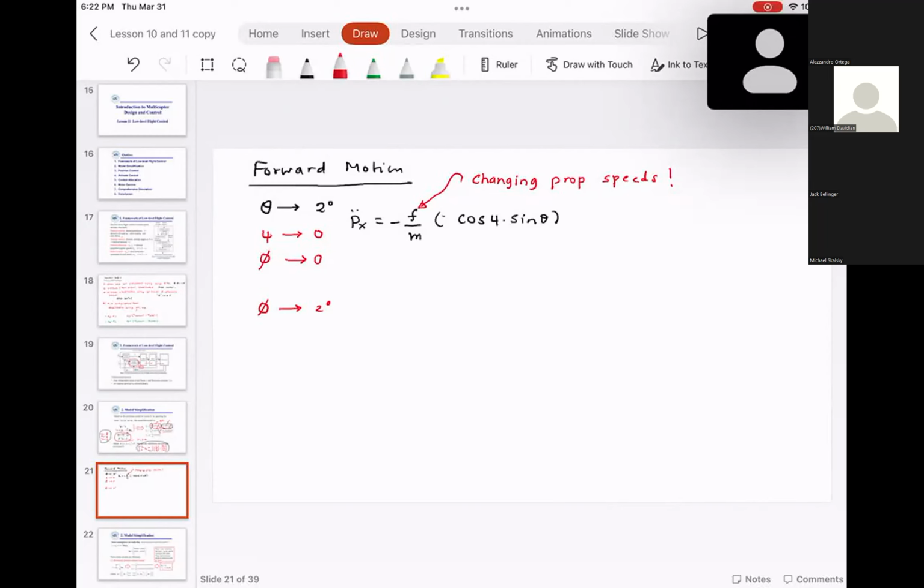So I hope that you will build that Mambo pendulum, and then I want you to observe that, assuming you are able to get those coefficients correctly, your Mambo would be stabilized for maybe 10 to 15 degrees. But as soon as you rotate it beyond 25-30 degrees, you will notice that rather than PID stabilizing the system, it would destabilize the system.